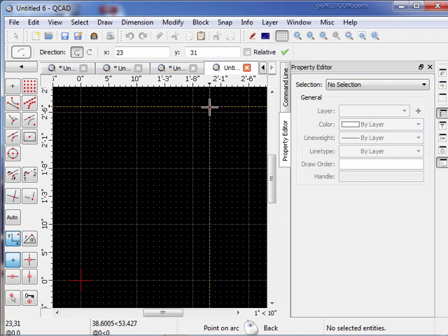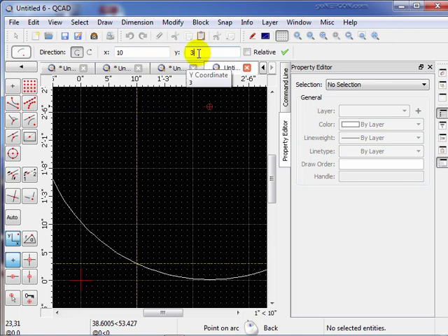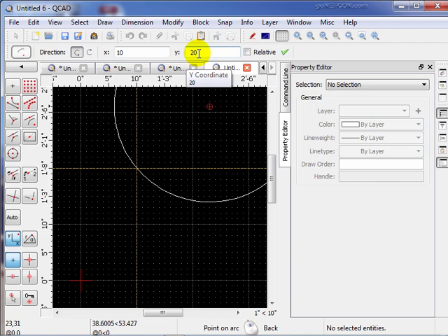Notice the arc's up here. So we're going to bring it down. We'll set the radius down here. Let's see, what's that, 10x, 20y. So 10x, 20y. Notice it's showing you as we're typing what we're going to end up with. There's our 10x, 20y. Once again, we've got to set that value. It's asking for a point on the arc, which means the radius. We're going to click this to set that point on the arc.